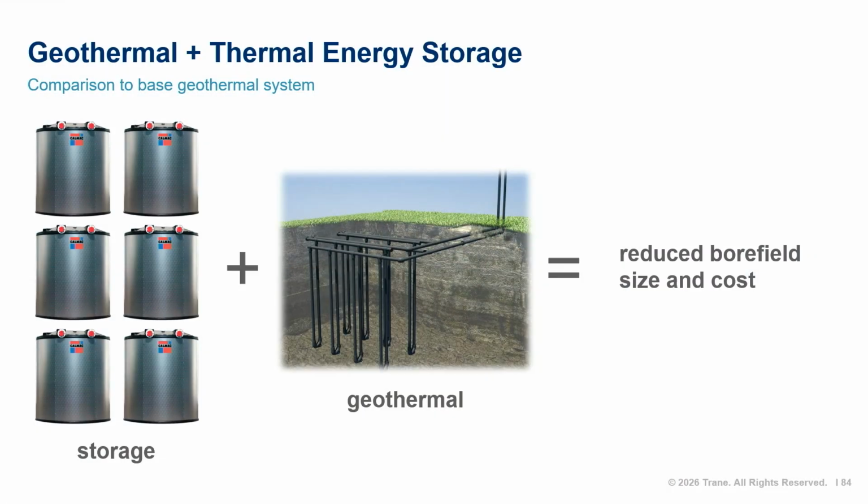Our first system concept is adding thermal energy storage to a geothermal system. A big driver for this is reducing the cost of the system. Thermal storage tanks are significantly lower cost than drilling bores. The tanks could be integrated into the geothermal loop and used with or without the geothermal loop. Maybe a Borefield loop was undersized and tanks can be economically added to the system to bring it back into ideal operation. Careful attention must be paid when it comes to controls to balance the field loop and the tanks.